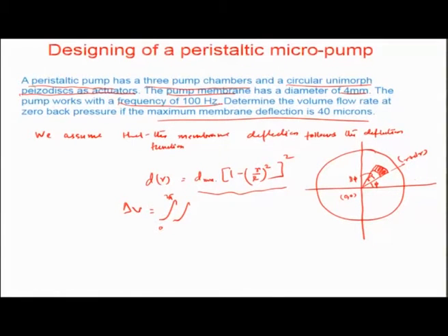And so, the best idea would be the delta V in this particular element can be represented as the deflection at the particular point. Because of the miniaturized nature of the dr and the d phi, we assume this element to have a total breadth of dr, okay, a total length which is given by r d phi, okay, r d phi is the length, because obviously d phi is the angle which has been moved and by a radius r,